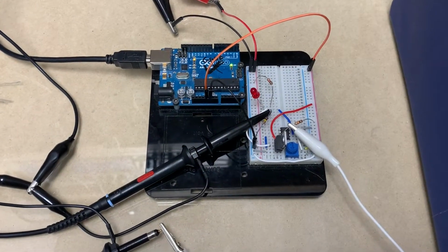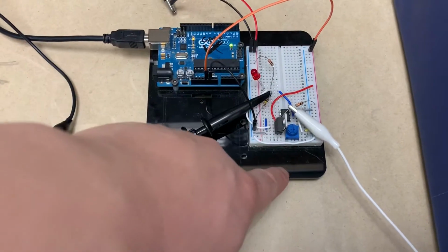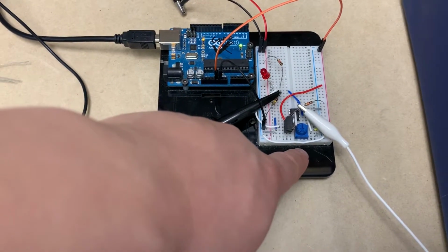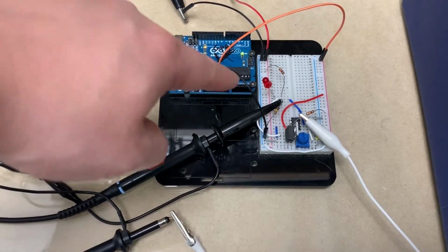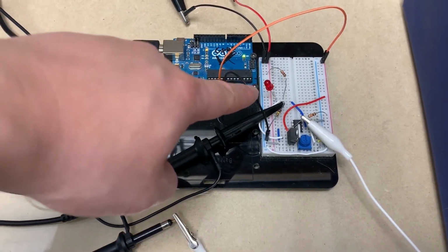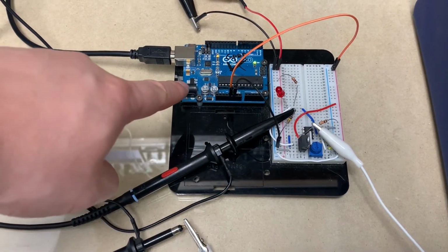Now that we have our circuit assembled with a MOSFET, a comparator, and also a potentiometer so that we can set the comparison voltage, now we can turn that SPAD signal that we have, those spikes, into a digital signal that our Arduino here can read.